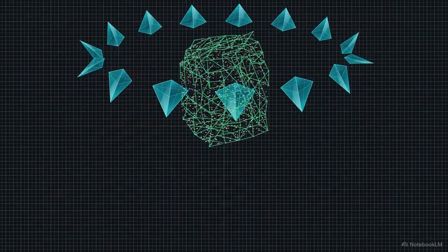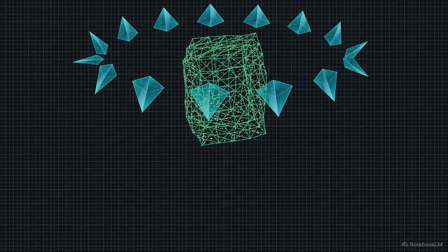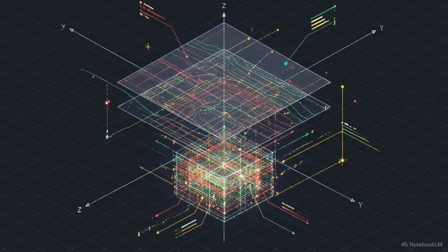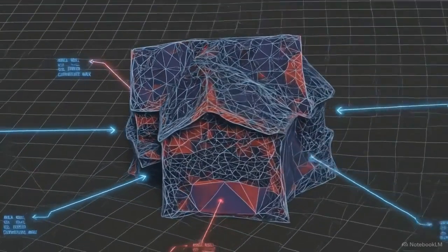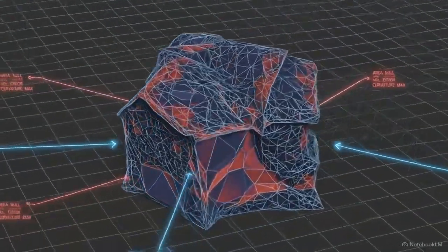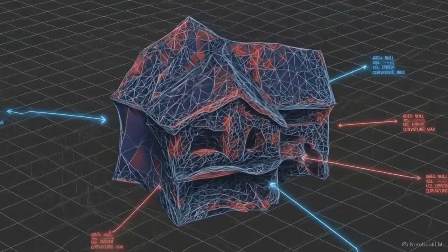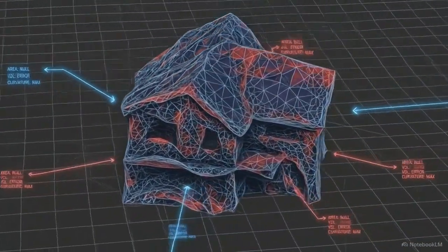Next, Open3D utilizes TSDF Fusion to merge those sparse point clouds into a solid mesh. TSDF Fusion is a 3D reconstruction technique that averages multiple depth maps to build a single, continuous surface. This rotating view shows why raw photogrammetry fails. The resulting surface mesh looks melted and mathematically imperfect, making it useless for precise construction quantities.